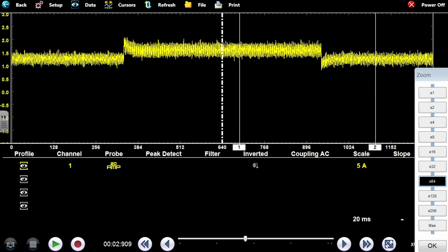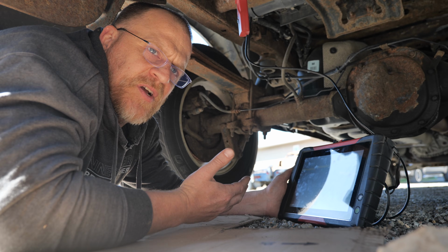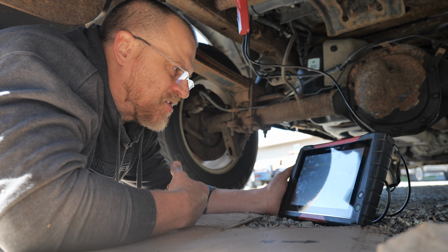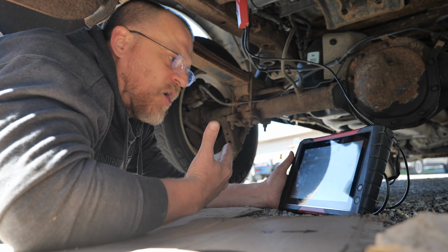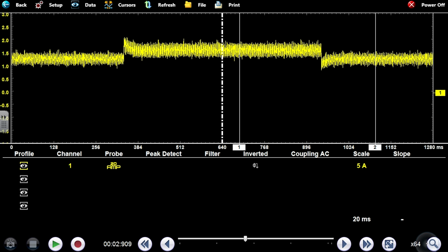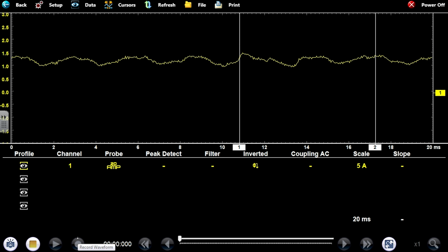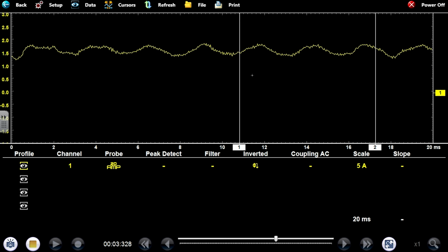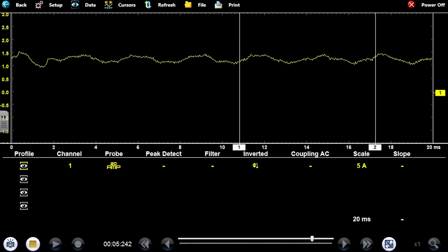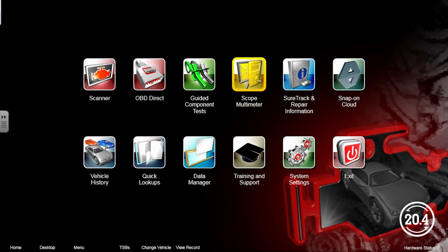Yes, this amperage is much lower than I'm used to looking at. A typical multi-port system, you're looking at amperage that's 4, 5, 6, even higher. My truck, for example, is like 9 or 10 amps. That's a Chevy Silverado, but it's running at full speed all the time. This one is being pulse width modulated. Let me see if I can change pressure on the scan tool and show you a higher amperage. Our amperage average is between 1.5 to 2 amps, roughly, right?